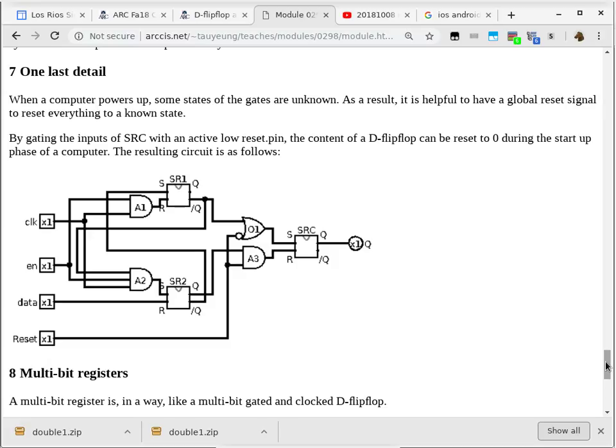Probably not. So this is why we need this particular reset pin, so that we can say, oh, you are just powering up. Hold the reset pin for X many milliseconds. So all the devices, not just memory, every single device, your processor, your chipsets, all the PCI cards that you have installed, everything in your computer, they're all connected to a system-wide reset pin. When the reset pin is a 0, it's telling all the devices in your computer to go to your reset state. Everybody, go to your reset state.